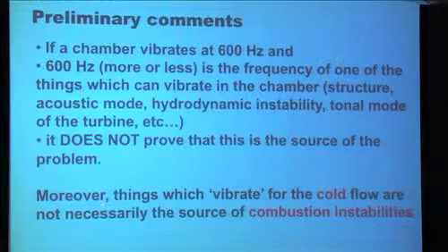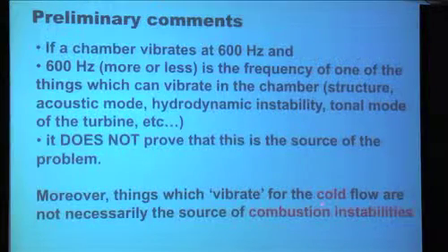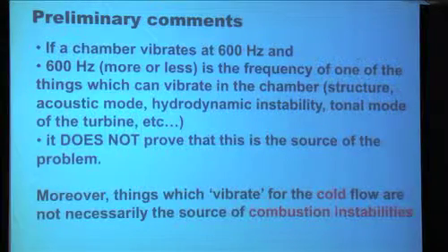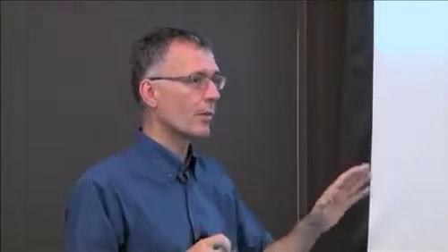And the other thing which we see quite often is that things which vibrate for the cold flow, before you ignite the flame, are not necessarily the source of combustion instabilities. Unfortunately, because all these phenomena have similar ranges of frequencies, it's quite easy to be confused. And I will give you examples where really we are not helped there, because there are many cases where these frequencies actually match, but they are not the source of the problem.